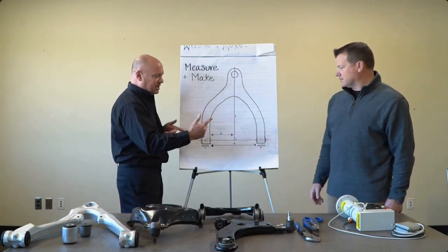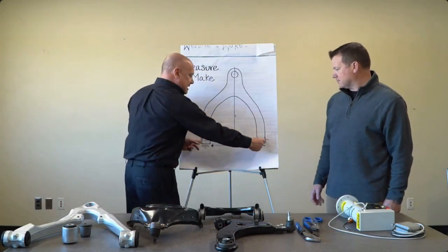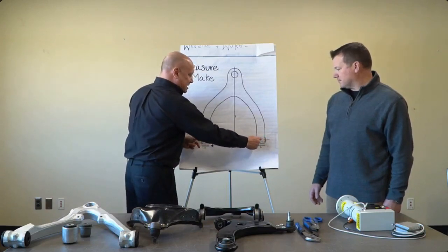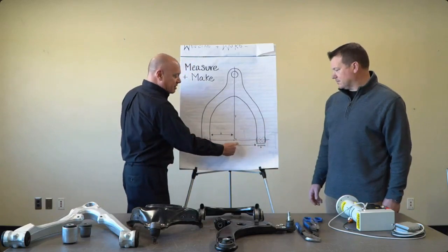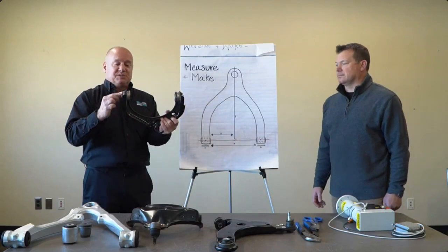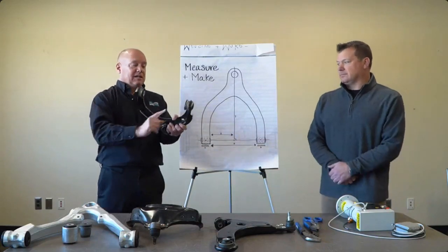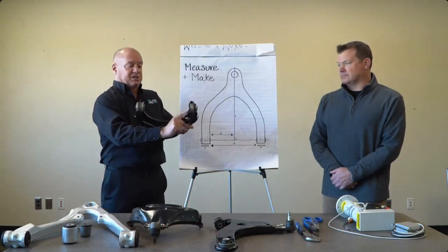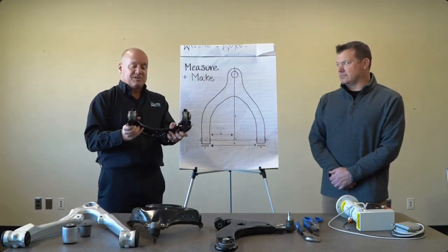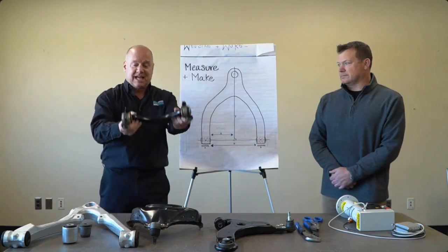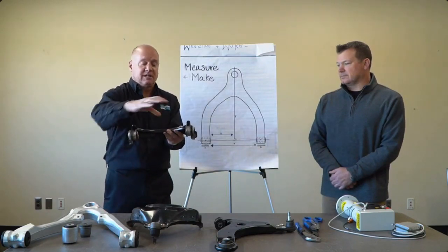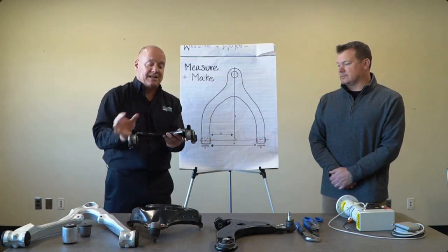We're going to focus in our explanation on the relative distance or relative placement of these bushings for dimension B. If you think like a normal control arm, these bushings being pressed in, the critical dimension is from the face of this pin to the face of this pin. That's where it interfaces with the vehicle. This slides over the frame of the vehicle. Bolts are put in here, and it's attached to the vehicle that way.